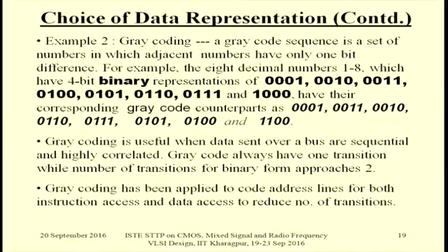Okay, so gray code is useful when you have got sequential access of data. But of course, the branches will be there, and there some violations will be there. Okay, because branches cannot be avoided. And for the data access, it is not possible to have a good amount of power saving, because successive data will definitely be unpredictable and random. So whether you take binary representation or gray code representation, we cannot predict that gray code will give us good result as far as power reduction is concerned.